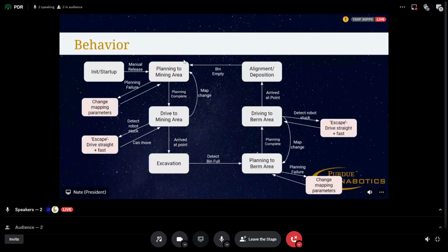Another thing is, are you assuming that would be a manual control, like a correction? No, okay. This is the behavior cycle for the autonomy. Okay, because since we have closed loop velocity, meaning that we want the wheel to go a certain velocity, and if it's not, that means it's stuck. Then the control feedback is to increase power.